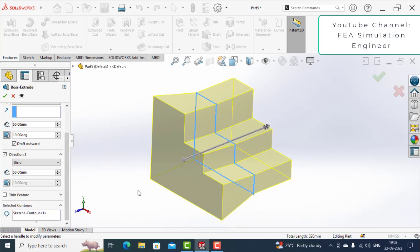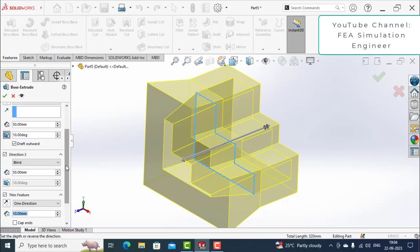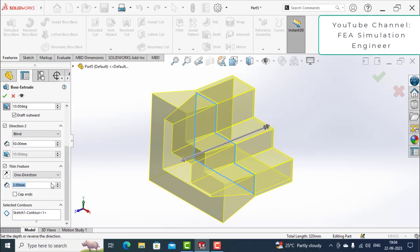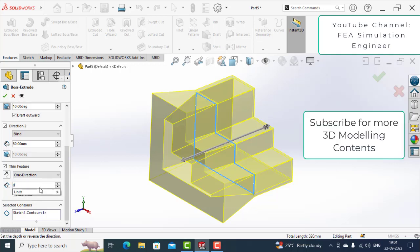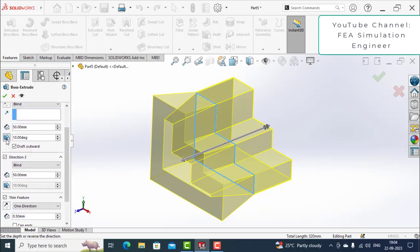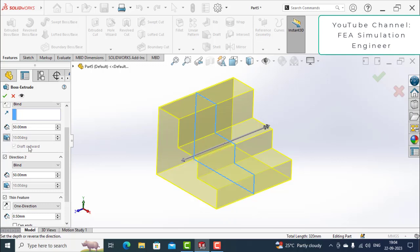The whole body can be accepted here, otherwise you can verify one or more features. This is the thin feature, and you can change the thickness here. Let me take it 2 mm, or we can take 0.5 mm, and because of this draft it is not showing properly, so I am switching off this draft.